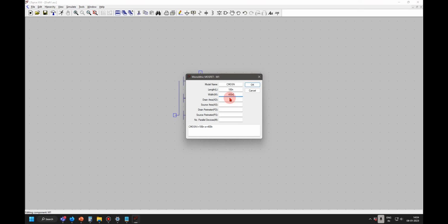In this course we are going to learn how to set the width for different circuits, whether analog or digital. We are going to assume length is 180. That is how the circuits are actually designed, and then to achieve the desired performance, we use width as a variable. Length is also variable, but we fix it at 180, the minimum. For analog circuits, we can increase the length because increased length will give you higher output resistance. We'll see that once we learn the theory. So W and L are variables given to the designer.